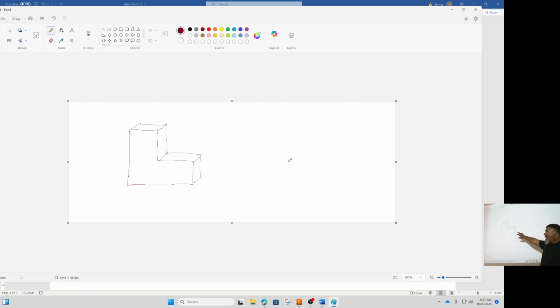So by hand, oblique's the easiest, especially if something's flat and you just need to add a little distance to it, or it has some simple cuts. It's pretty easy. Isometric is the easiest on the computer because that's what it does automatically. The computer will also do perspectives in Fusion, but we usually won't do that on drawings. We'll do that on renderings, the photoreal stuff, because we want that to look more realistic. But drawings are isometric, or by hand, oblique's an easy way to make it look like that.